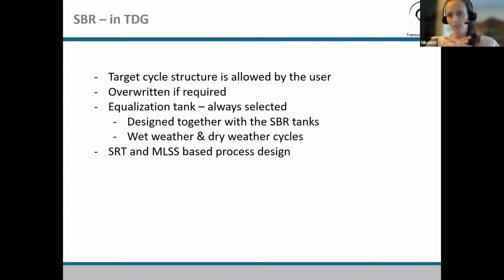The main process design in the background is an SRT and MLSS based process design. As you have seen, the MLSS can be given, and also the SRT can be given. Based on different yield values, we calculate the sludge production as well, and this will lead to the required process volume.